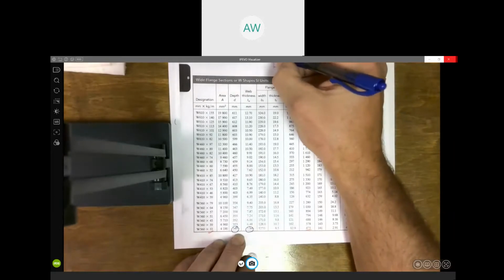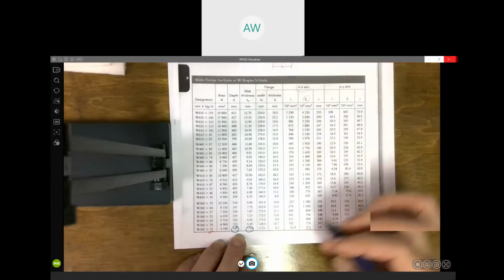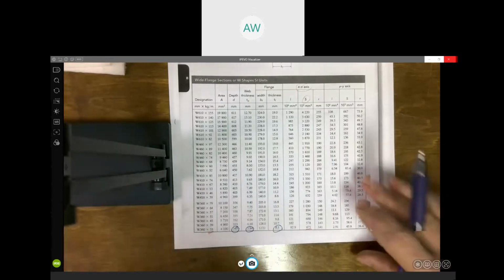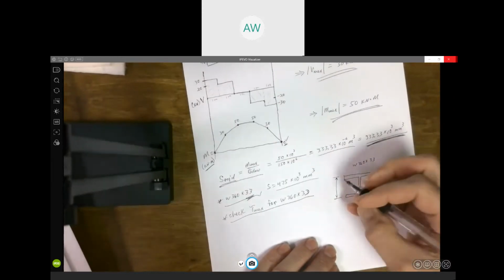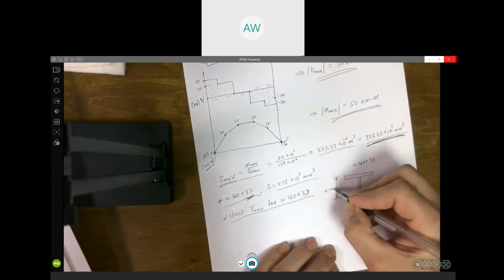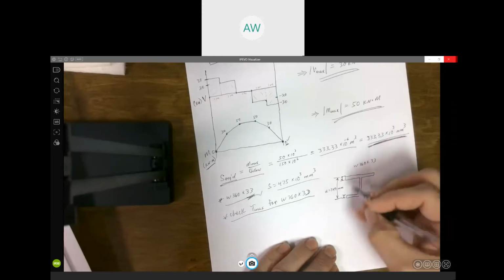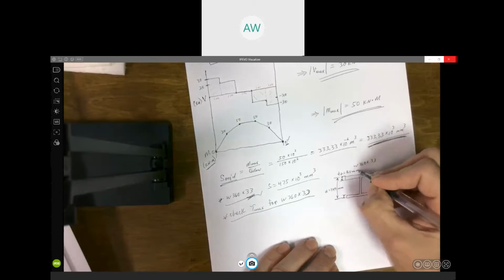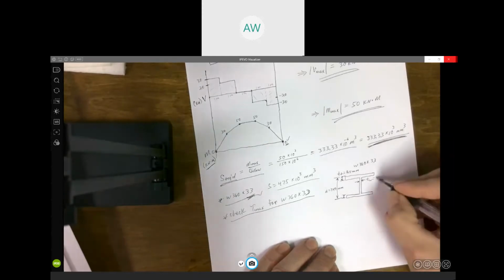And to get the area of the web, we got to subtract off those two flanges. Right? So we got the thickness of the flange here and here. It's 8.5. Right, so now I'm going to go back to my picture over here. I'm going to add those numbers in. D here was 349 millimeters. The thickness of the flange, 8.5 millimeters. The thickness of the web, 5.84.